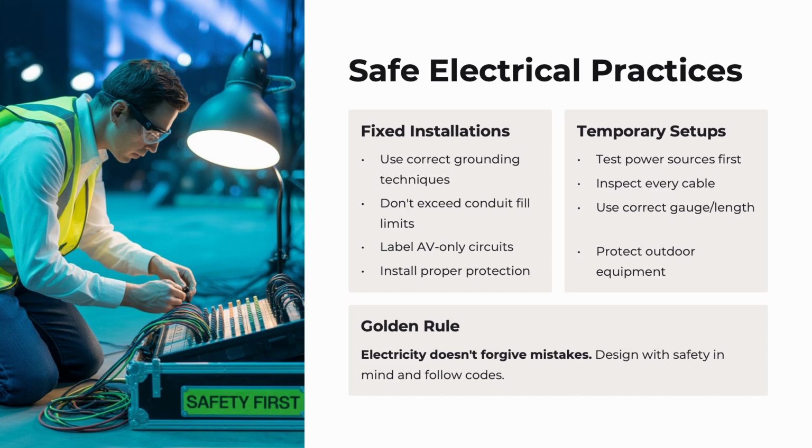Remember that grounding protects users and systems from dangerous fault currents. Using interrupters or RCDs is important to detect faults and cut power instantly. Double insulated gear doesn't need grounding, but it must be used as specified. And isolated ground systems prevent noise and hum in Pro AV installations, and never ever bypass grounding. It's not just bad practice, it's unsafe.